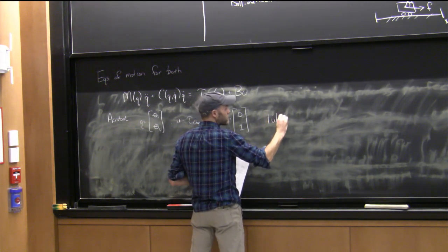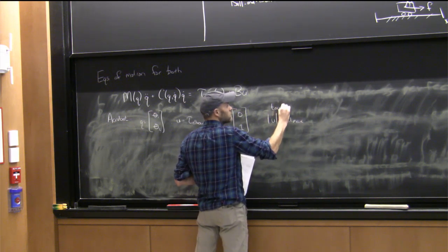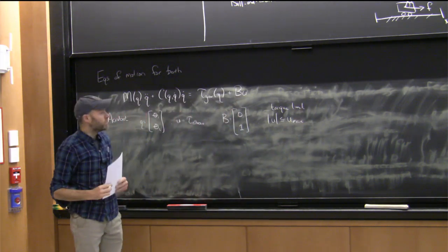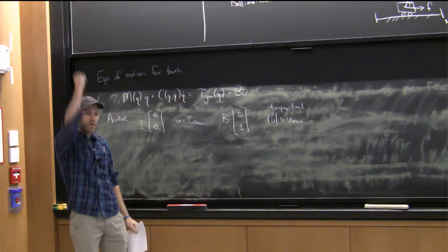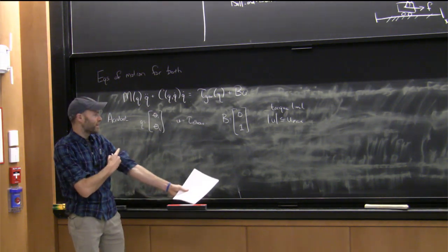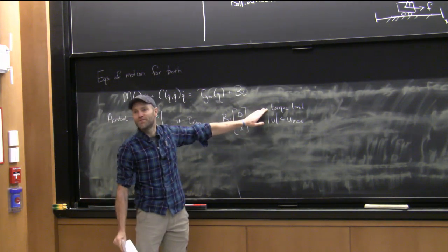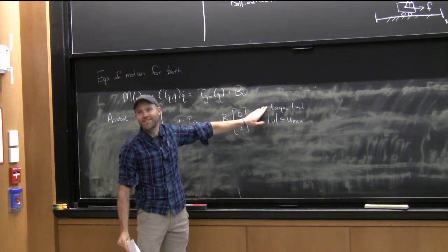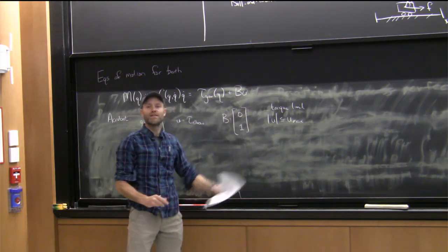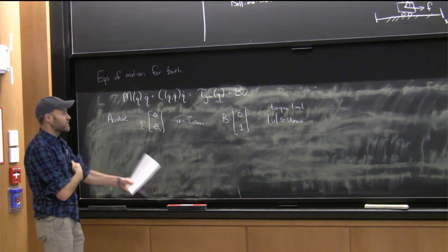And to keep it interesting or reasonable, we're going to put a torque limit on there. You sort of have to do that, otherwise you can make things happen that look physically unrealistic. Which, by the way, is what happens in all the videos of deep RL, right? They forget this part, and then things look ridiculous, and that's why. But good luck running that on a real robot. You need torque limits, and it reduces the class of possible solutions considerably.